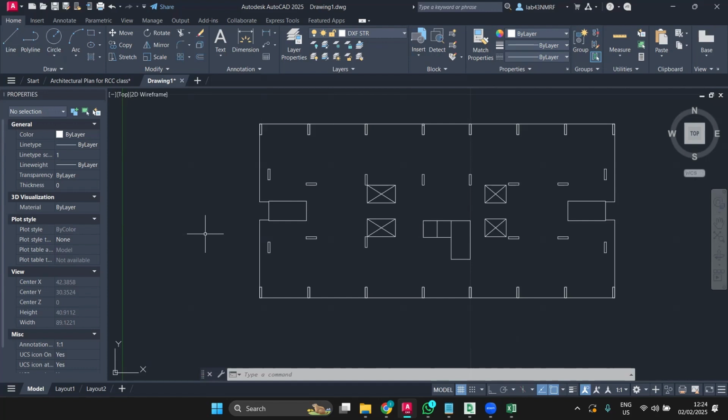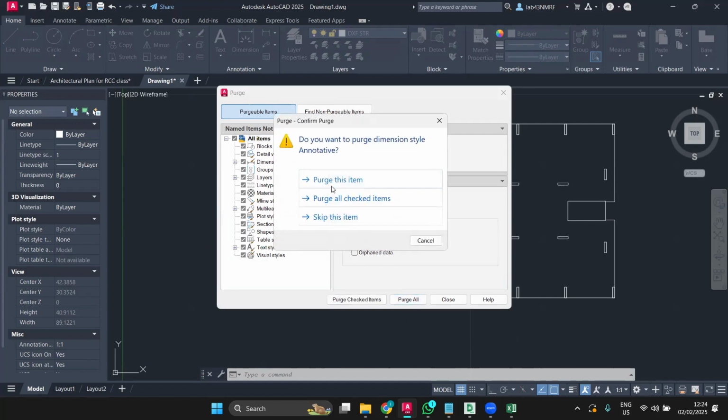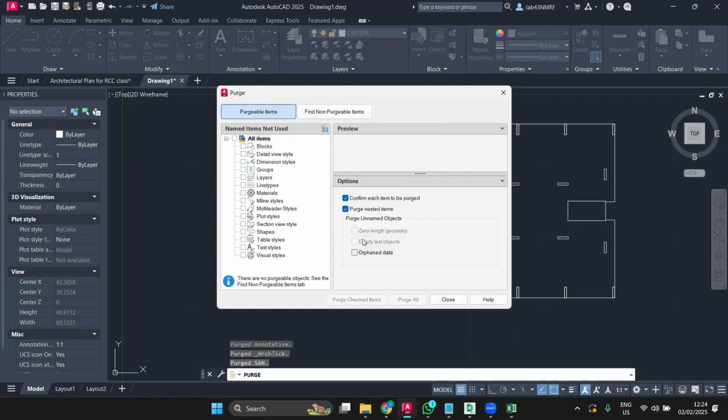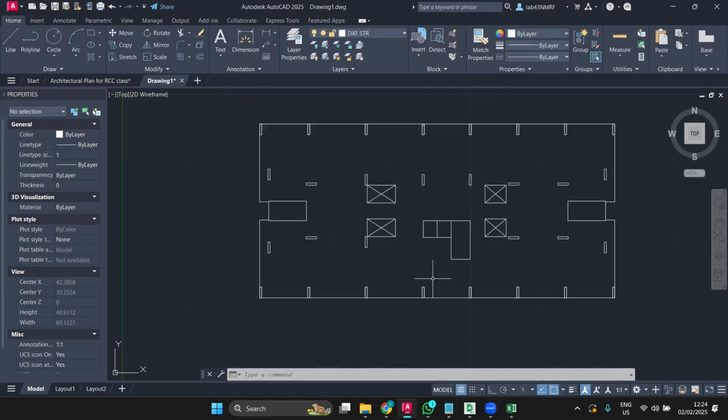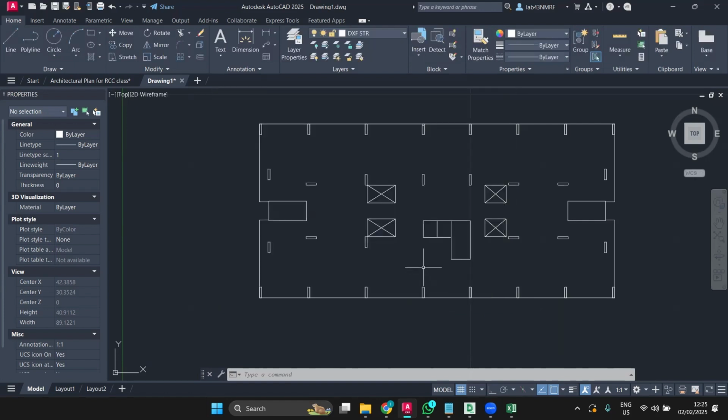It's fine, right? Explode all the lines. Okay, now purge. P-U-R-G-E, the purge command. Make sure none of the points or lines or anything unwanted is there in the CAD; it will remove them. Do purge two times, because sometimes one time does not cover everything. Understand? If it is not showing anything, it is fine. It is all purged.